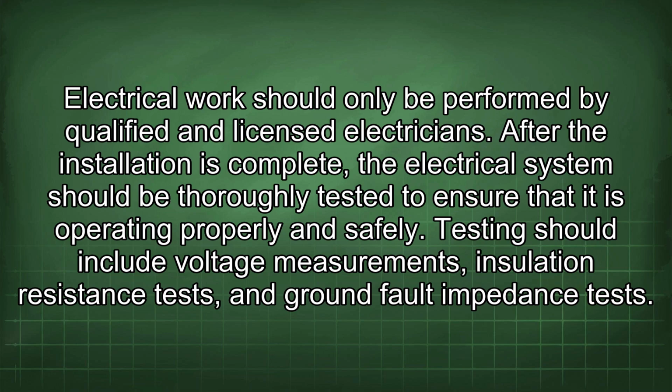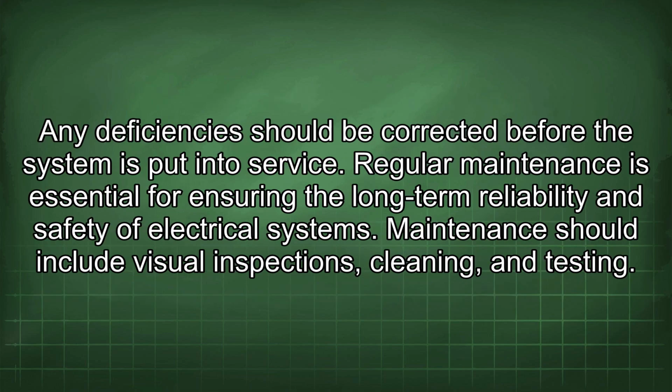After the installation is complete, the electrical system should be thoroughly tested to ensure that it is operating properly and safely. Testing should include voltage measurements, insulation resistance tests, and ground fault impedance tests. Any deficiencies should be corrected before the system is put into service.